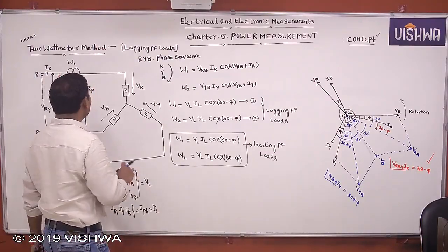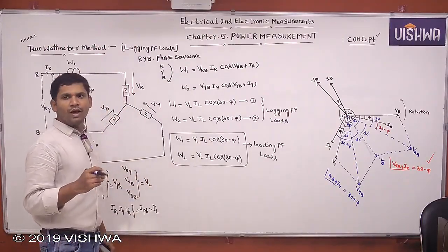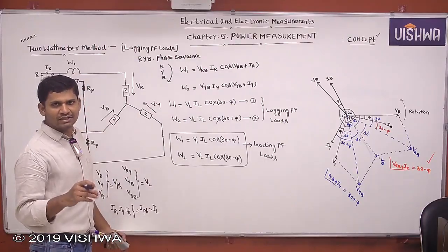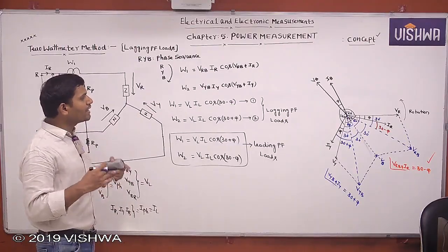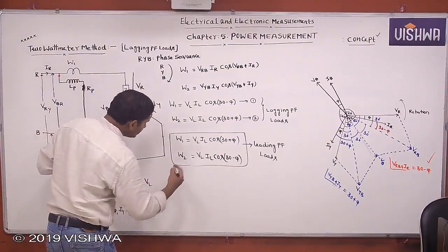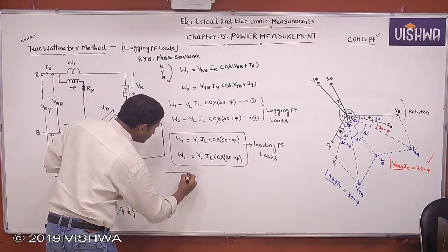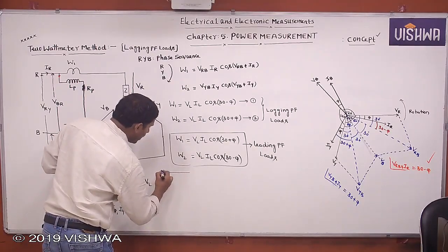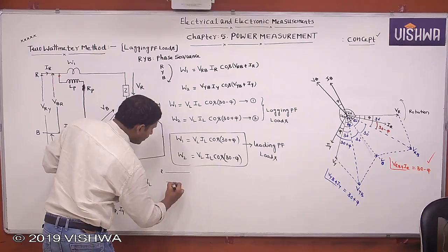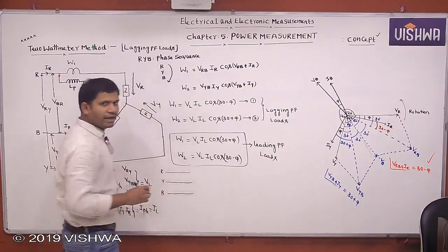But if the wattmeter connections change, if the phase sequence changes, how the wattmeter readings will change, that you concentrate on. Every time no need to draw the vector diagrams, all these. Directly also we can answer. Yes, one observation here. So listen please. Let this be R and this is Y and this is B. RYB phase sequence. We connected like this.